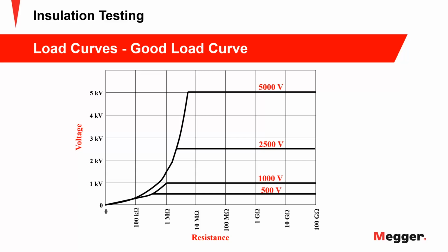So once you get above a megohm, or sometimes a little bit higher for equipment that's higher rated, you want to follow basically the 1 megohm rule. Once you get up to a megohm, you want to have full voltage. Below that, your equipment may be getting ready to break down, so your voltage can decay, and that's fine. But let's look at the next slide.